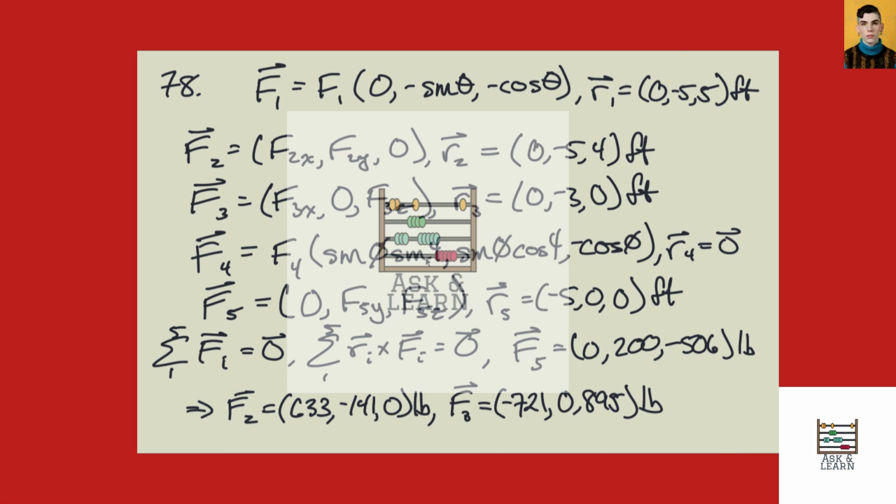Intuition, when you have geometry this complicated, starts to break down. And you can see that basically constraints at B and C need to carry all of the Z load. The constraints at A and C need to carry all of the Y load. And the constraints at A and B need to carry all of the X load. Basically that's saying that the sum of the forces must be 0. So there's your answer.